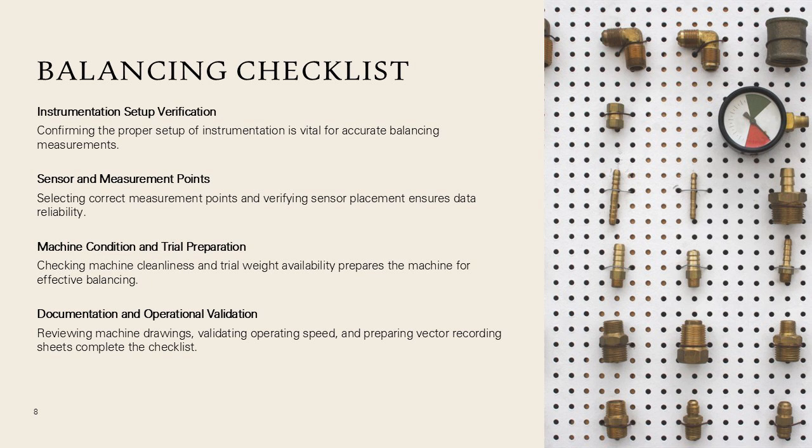It includes confirming instrumentation setup, selecting appropriate measurement points, verifying sensor placement, checking machine cleanliness, confirming trial weight availability, ensuring accessible correction planes, reviewing machine drawings, validating operating speed, and preparing vector recording sheets.